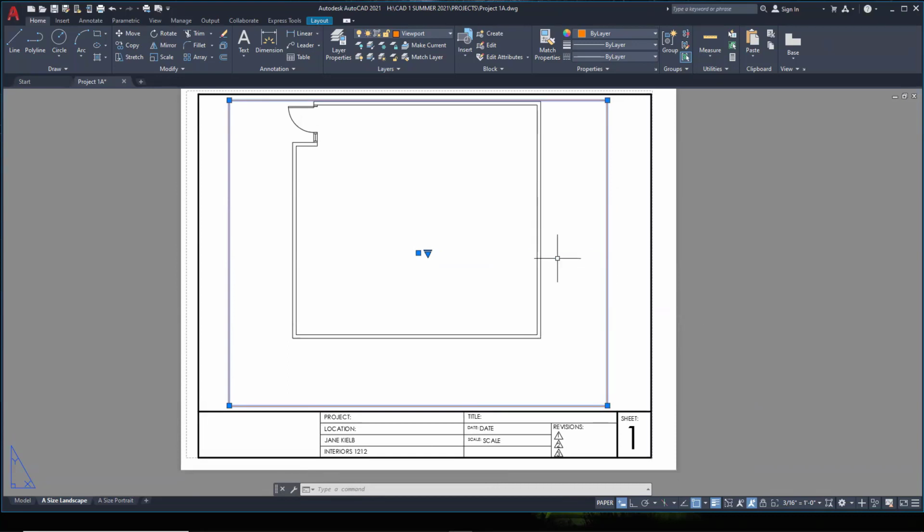This time I'll click on model space to get in there. And now you'll notice that my viewport is highlighted and I have my UCS icon and it says model space down here. So I know that I'm now in model space, or sometimes I'll call this white model space because it's model space, but it's white rather than the black model space over here.